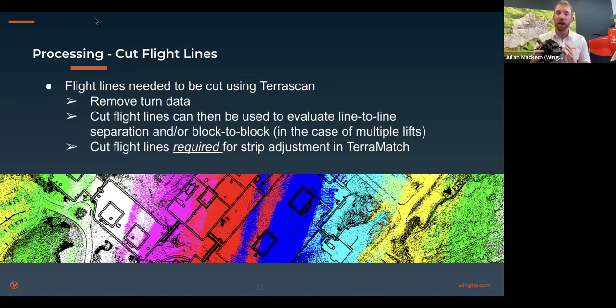And then there's a question coming in about whether it also has an RGB camera. We have decided not to put an RGB camera, so it's actually light enough to be able to map very large missions and to get accurate data in every mission. But also what we realize is that most of the customers who are flying out there with LiDAR and who would also like to have a colorized point cloud, they also want to have a good quality orthomosaic. And for this, you need to always have a very good RGB camera. And that's why we decided to not go for a small RGB camera, but rather really go for a good LiDAR that can map a big area in a short amount of time.